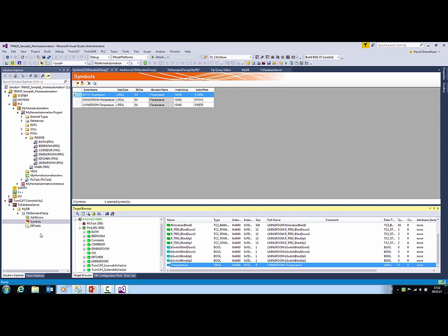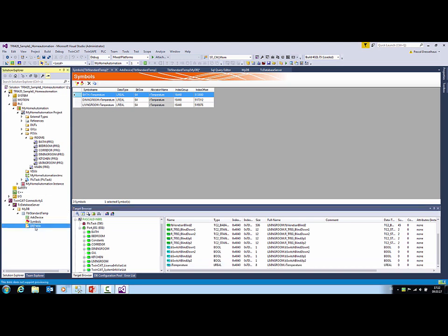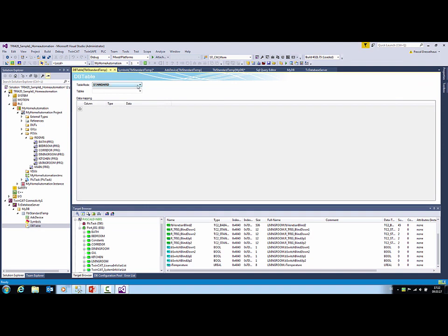Then I can go to the table, and I can choose one of the tables. I can choose the table mode, standard or custom. In this case I will choose the standard table structure, so I choose standard. And then I can choose one of the tables. If I choose the wrong table, like custom, then it says directly, hey, warning, this is not the right table. Please choose another table, and then I can move again to the standard table, and then it says everything is okay, it's fine.